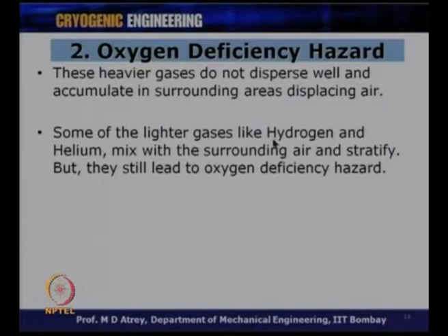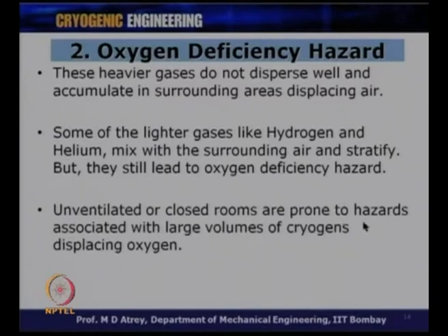So, this can happen with lighter gases like hydrogen and helium, they will mix with surrounding air and you can have some stratification depending on the density differences. We can have some oxygen rich, oxygen deficient, hydrogen or helium rich regions or whatever. You can have oxygen deficiency hazards in these cases also. Unventilated or closed rooms are prone to hazards associated with large volumes of cryogen displacing oxygen.